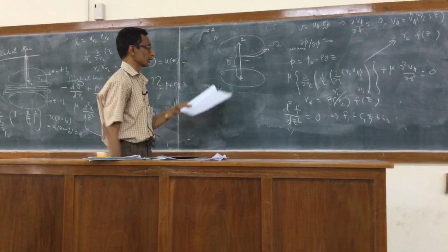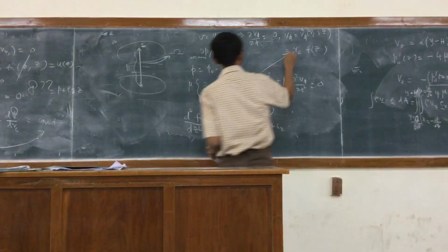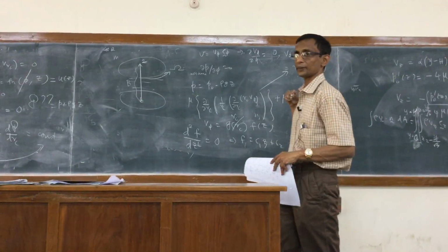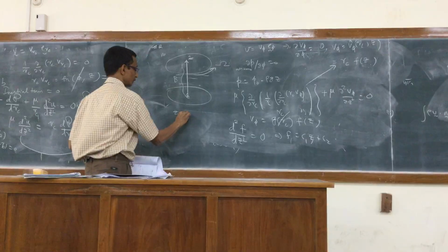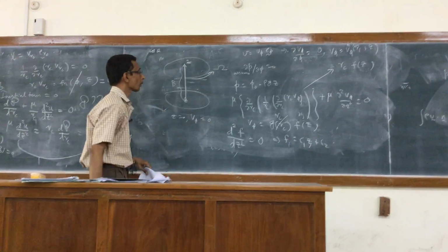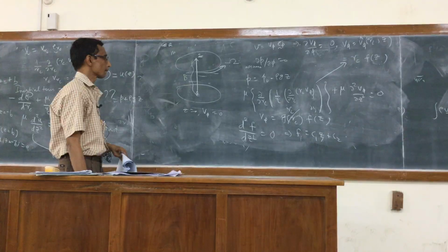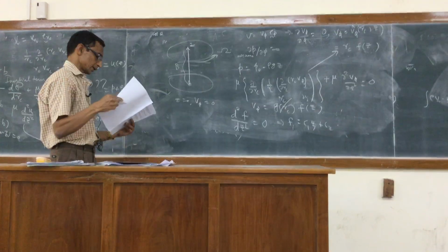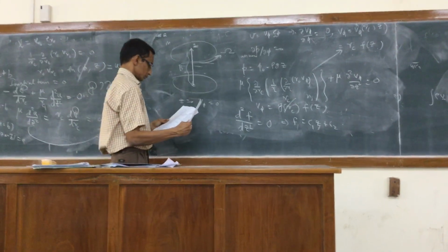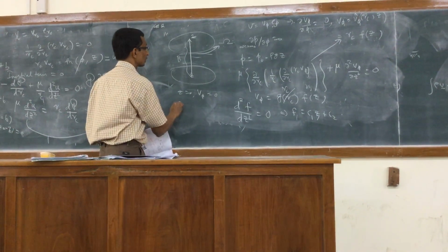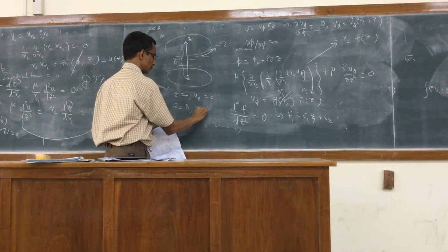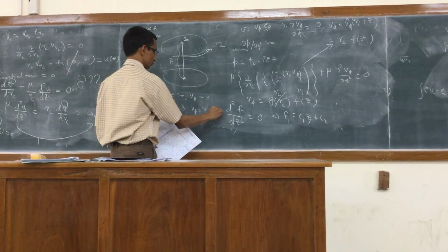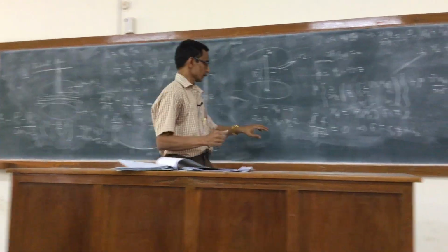And if I now apply these boundary conditions, clearly, because it's the product of r_c times f, right? So v_phi is 0, f must also be 0. So the boundary conditions are z equal to 0, v_phi is equal to 0. At z equal to b, v_phi will simply be r_c times omega. Maybe that is why he says that this form is justified.